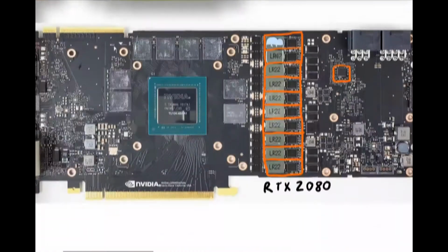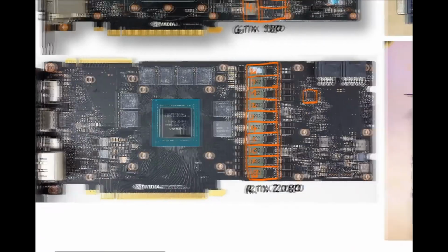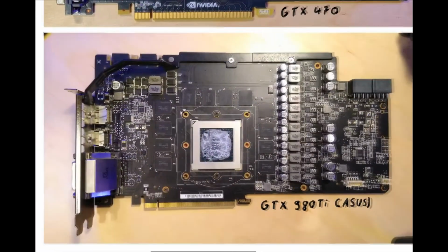So yeah, back to this one. We see 1, 2, 3, 4, 5, 6, 7, 8 vCore phases and 1, 2 VMem phases. The PWM controller is a UP9512, which is an 8-phase controller. VMem VRMs generally don't get doubled or use the big setup. For VMem, it's 99.9% of the time the amount of phases which you count as inductors. So this is a 2-phase. I know for a fact that this is a 2-phase, but you don't really have to look up the PWM controller to find out.